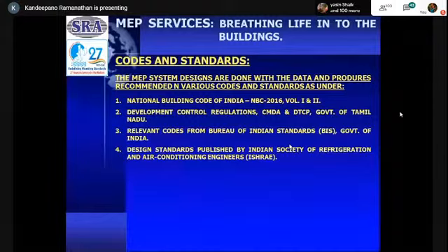This is referred to for gathering information like what is the ambient temperature at various locations of the country, like Chennai, Madurai, Coimbatore, New Delhi, or name any important city. The design summer temperature, monsoon and winter temperatures will be given there, so that you can do your air conditioning system design, what is so-called heat load calculations.